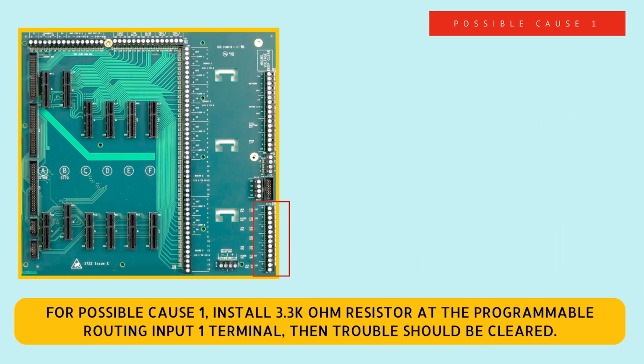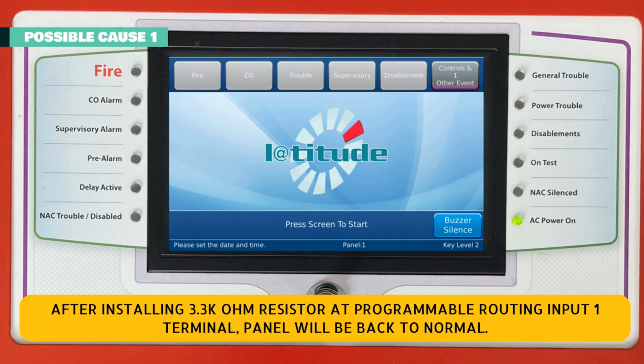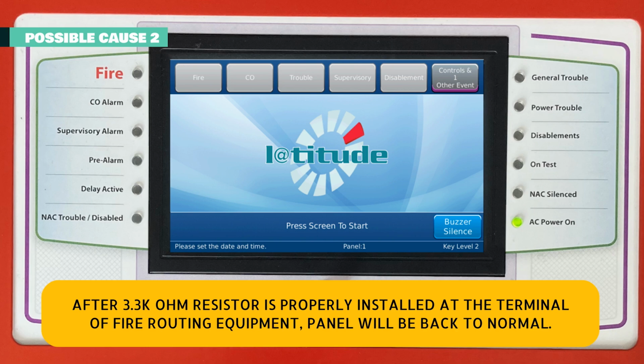For possible cause 1, install 3.3 k ohm resistor at the Programmable routing Input 1 terminal, then trouble should be cleared. After installing 3.3 k ohm resistor at Programmable routing Input 1 terminal, panel will be back to normal. For possible cause 2, if 3.3 k ohm EOL resistor is not properly installed at the terminal of Fire routing equipment, then install it properly and trouble will clear. After 3.3 k ohm resistor is properly installed at the terminal of Fire routing equipment, panel will be back to normal.